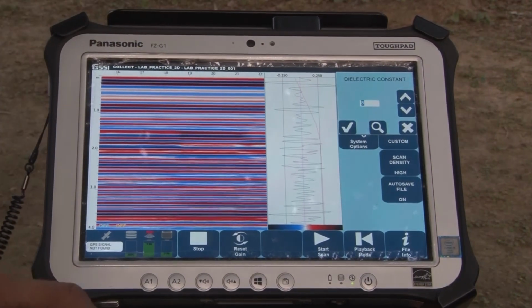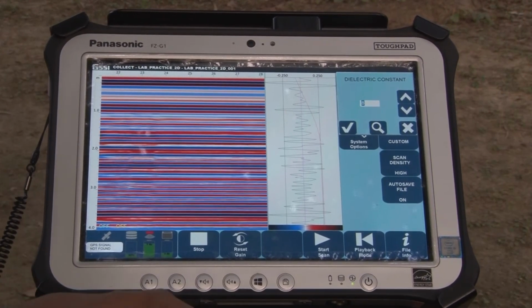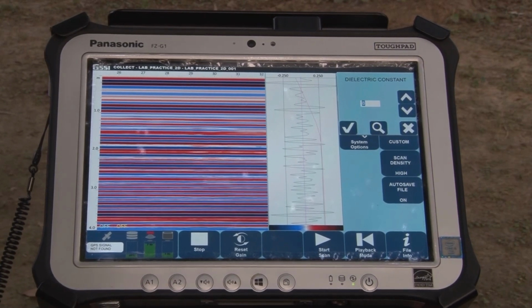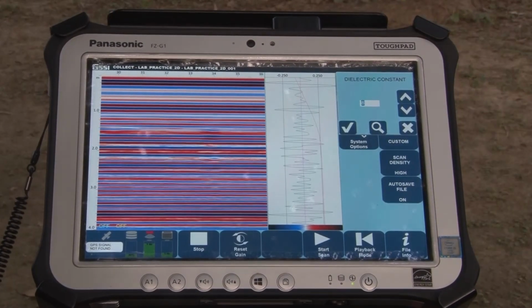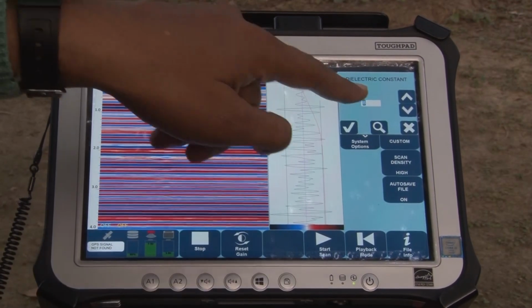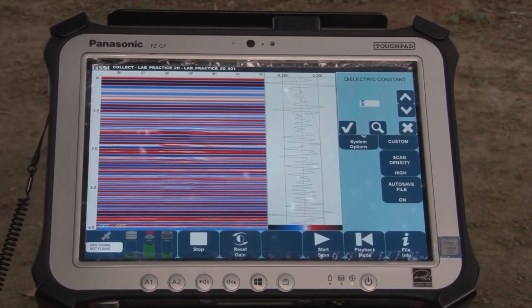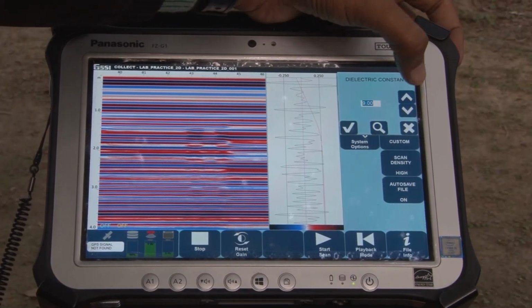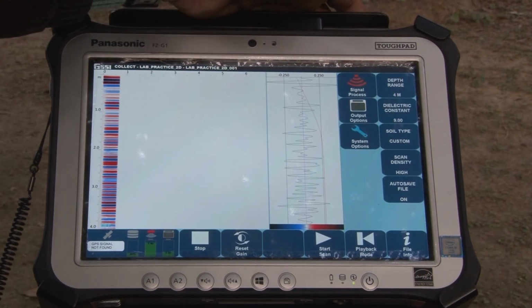As I have mentioned previously, there should be a clear-cut dielectric contrast between the target material and our medium. The medium is our soil as of right now. So the dielectric constant of soil is a very important parameter for the survey. As we can see, this is some kind of wet soil, and wet soil will have a dielectric constant of around 9 or 10.